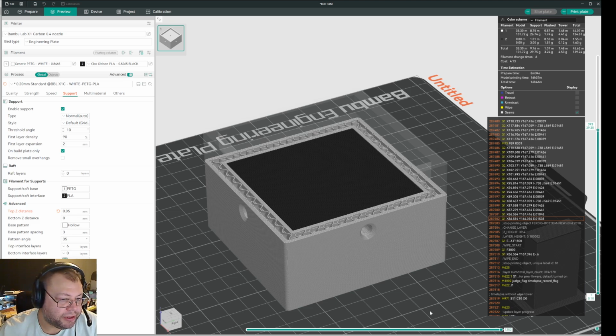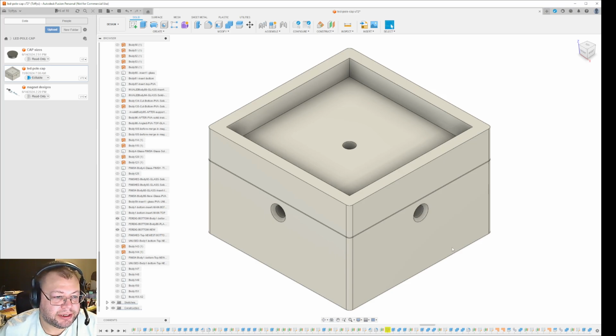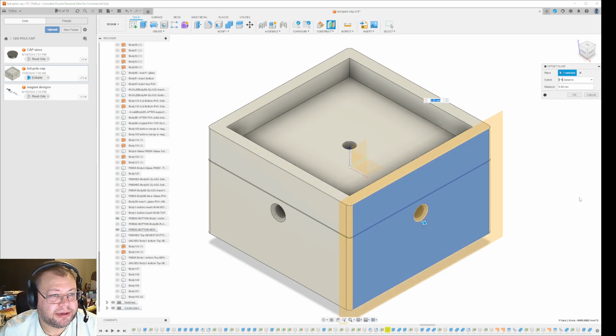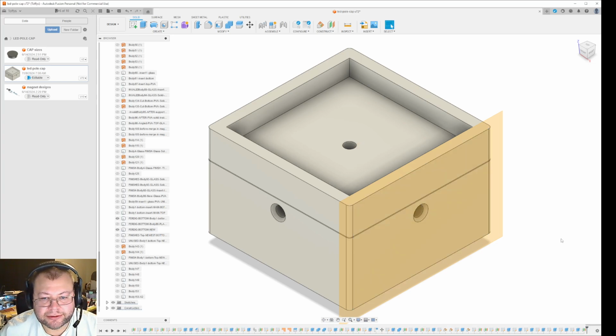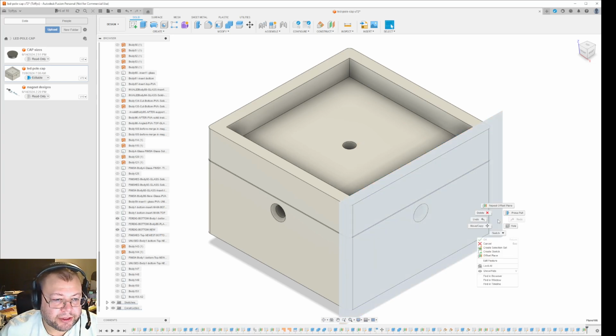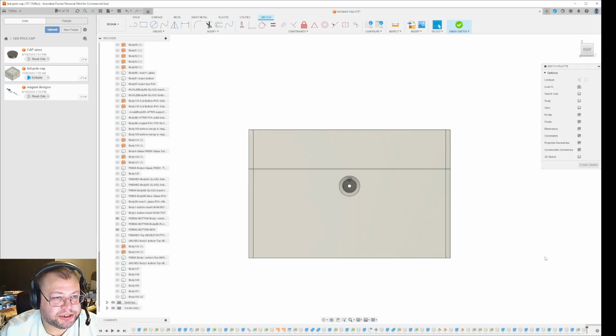So I came up with a tiny cheat in a way. For this you will need Fusion 360, or a similar program, which I have used here and made this in. So I'll bring myself back into here and I'll start with making a drawing plane on one side of the same cube. And then I'll create a sketch, select the outermost corners on each side, and project those.